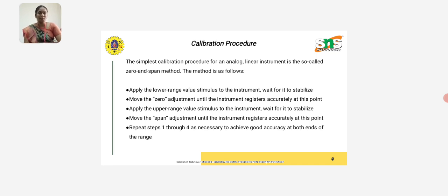The device to be calibrated should first be visually inspected for any physical defect. While calibrating, the device should be in its proper position, like upright, horizontal or vertical, properly leveled, and subjected to the same temperature and other environmental conditions under which it has to operate or is specified.